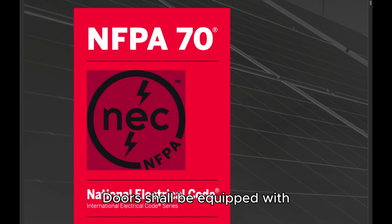4. Locks. Doors shall be equipped with locks, and doors shall be kept locked, with access allowed only to qualified persons. Personnel doors shall swing out and be equipped with panic bars, pressure plates, or other devices that are normally latched, but that open under simple pressure. 5. Transformers. Where a transformer is installed in a vault as required by Article 450, the vault shall be constructed in accordance with the requirements of Part 3 of Article 450.